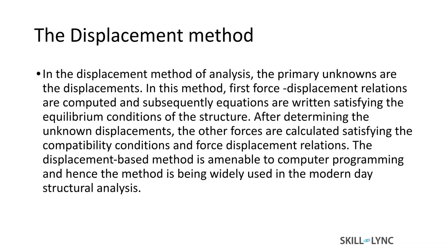So previously the forces were the unknown terms. Currently the displacements become the unknown terms, in terms of the load, by using the load-displacement relations. And these equations are solved for the displacements. Once the displacements are obtained, the unknown loads are obtained from the compatibility equations using the load-displacement relation.